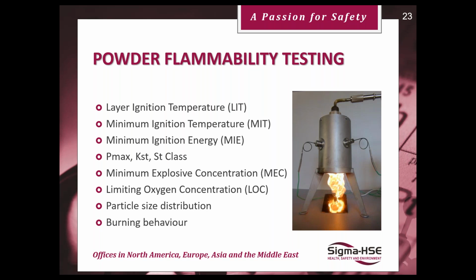We can also measure the minimum ignition temperature, which is the temperature required to produce ignition of a flammable dust cloud. It's a cloud phenomenon. The energy source is purely the temperature that gives sufficient energy to kick off that combustion reaction between the solid fuel and the oxygen.